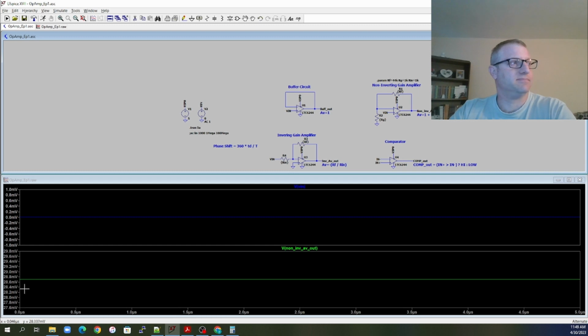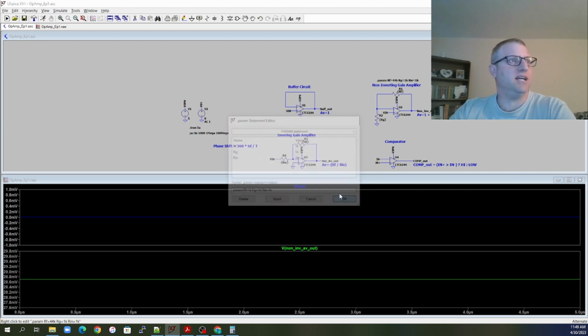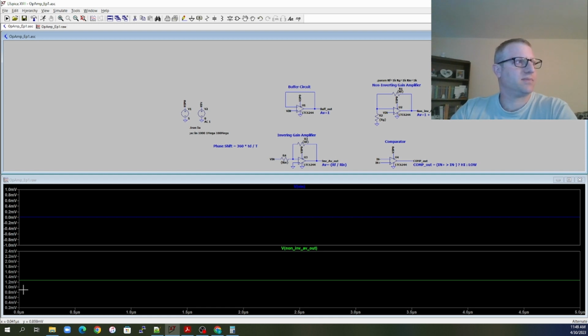And then what's our output? So with nothing on the input and a gain amplification, actually, let's go ahead and take our amplifier and make it a unity gain amplifier also. And so you can see that our output is about 1.2 millivolts, right? Based on the calculation that they're doing here for the simulation. So that's the voltage offset parameter.